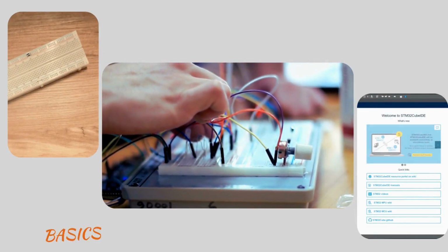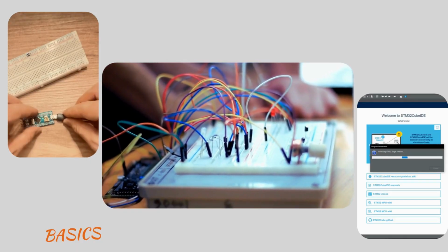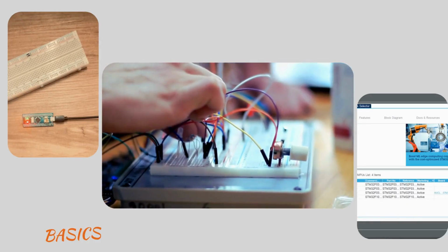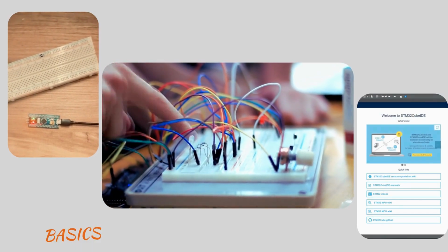Imagine starting with a blank desk, an STM32 board, a breadboard, and curiosity. But first, you'll learn the basics: how to set up STM32CubeIDE, connect your board, and blink your first LED. This simple hello world of embedded systems will give you the confidence to move forward.